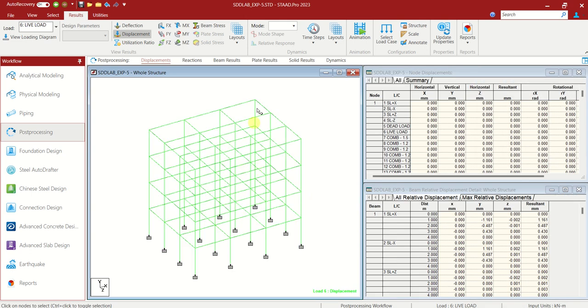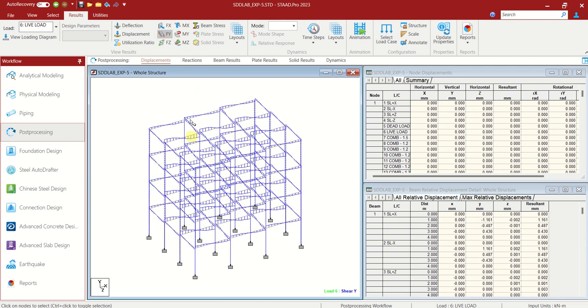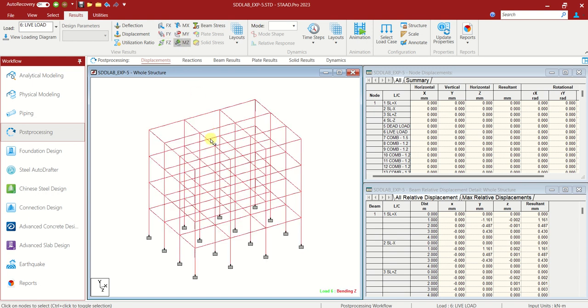So we have all these loads. So we can also see the moment forces. We can see reactions and beam results over here. Okay, first we can choose only one, and we can use the control and scroll up in order to scale it. F5, choose F1 and select other, press the control button and scroll up, and select this and choose the bending moment.